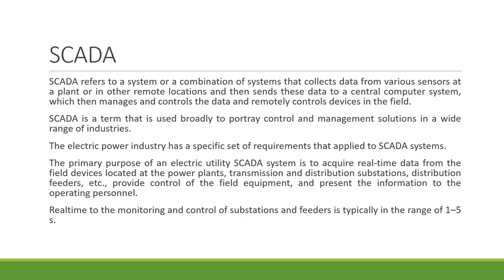You have placed sensors at certain locations, at your plant, at remote locations, and these are going to send the data to a computer placed at a central location. You can call it a central computer system, from where, according to the data, the control signal can be sent, and remotely you need not visit that particular location personally. Remotely you can operate it because IEDs are also there.